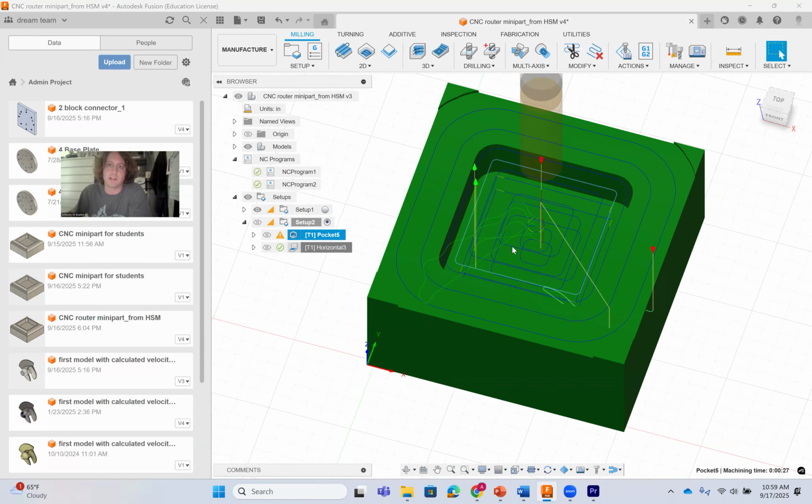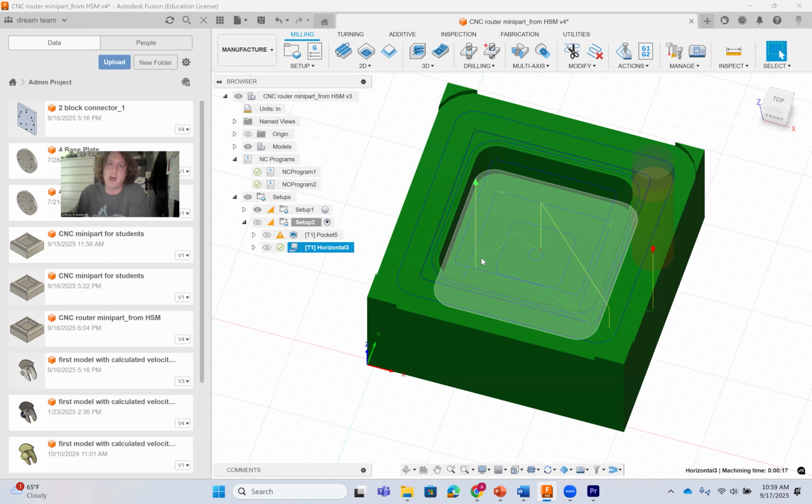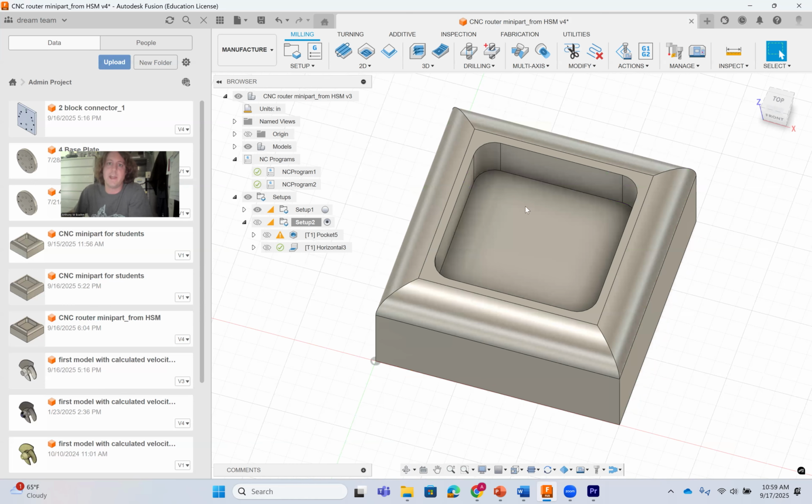And with the horizontal here, we're also doing tool outside boundary. So it's going to finish all that on the top and finish the flat part in the bottom. Okay. Now we're going to use a 2D contour and we're going to finish the sides. It should be said I could just unclick stock to leave and it would do the sides here, but I'm just trying to give you a couple examples on how you could finish